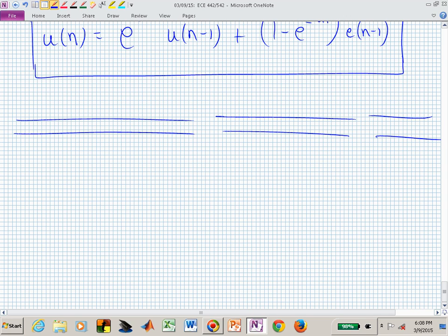So we're getting now into the control aspect. We've been doing a lot of modeling and filtering, discrete equivalence. Now we want to be thinking about how we establish the desired closed-loop poles in the z-plane, like we were comfortable with, maybe, if you've had an earlier class, the S-plane pole locations in an analog control class. If you haven't seen that, we'll try to make the connection now. And this is relating time domain behavior with frequency domain pole locations.